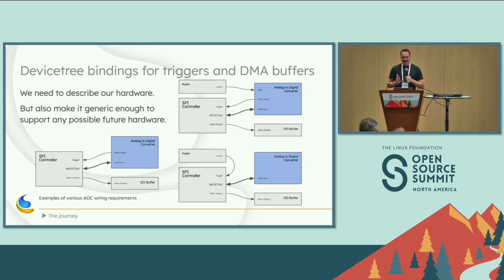In the end, as the maintainers say, the device tree is just describing how things are wired up. So if you draw it out like this, then it's going to be pretty obvious how you should make the bindings look. One of the things that came out of this is that we took the trigger source provider and consumer that you might have seen in the LED subsystem and made it more generic. So in the DT schema repository now, there are the trigger-sources and #trigger-source-cells bindings that are generic so you can use them anywhere.